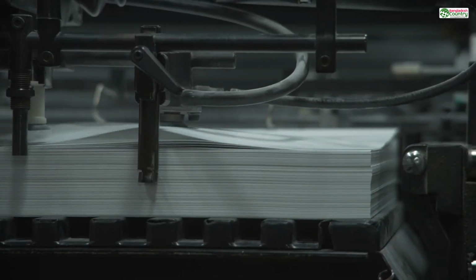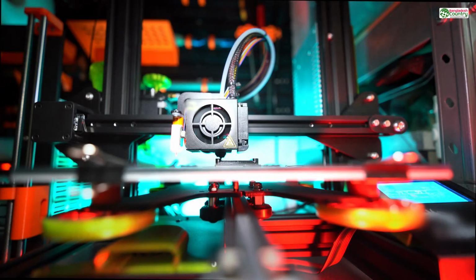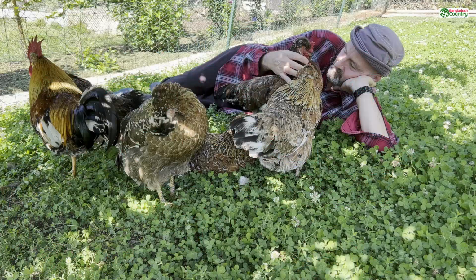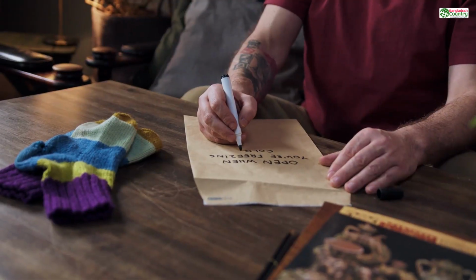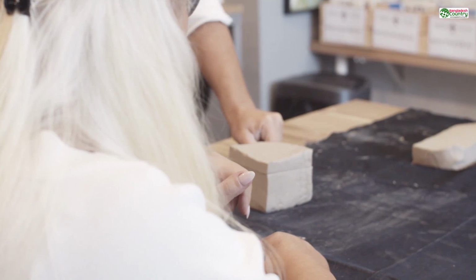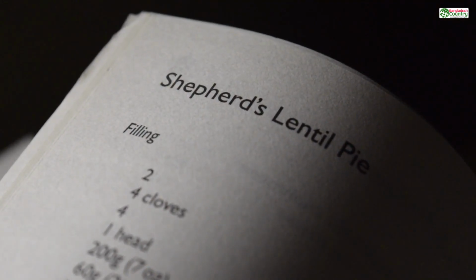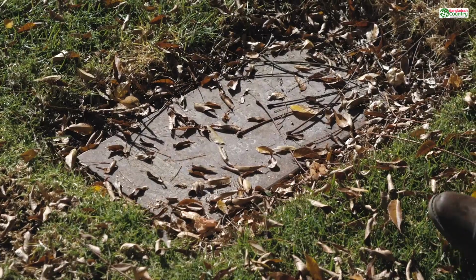Your printer nozzle has a specific diameter. It lays down a bead of plastic with a real physical thickness. When the slicer sees a zero-thickness wall, it has no instructions on how to build it. It can't make it exist. So, it usually just ignores it completely, leaving a gap in your model that becomes a catastrophic failure on the print bed.